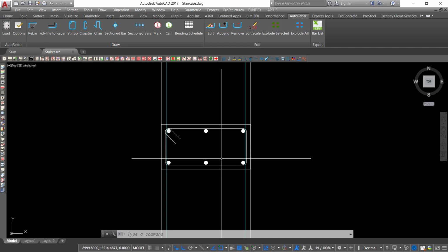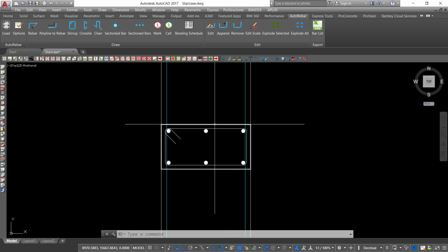Seeing the blocks will seep in moisture, we want now to fix or lay a DPC. A DPC is a damp-proof element that obstructs the moisture from entering the masonry or the brick wall, or the bricks and onto the floor of a building.